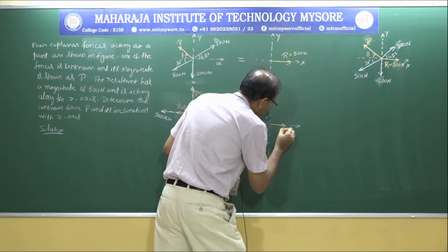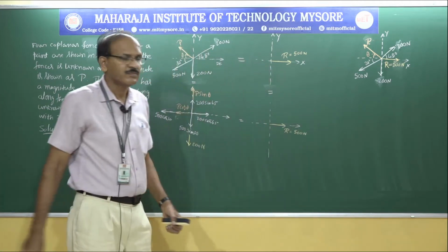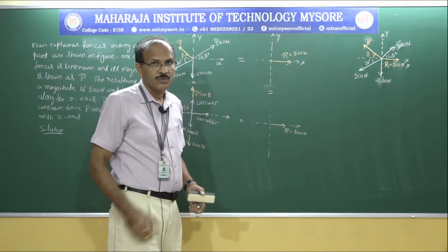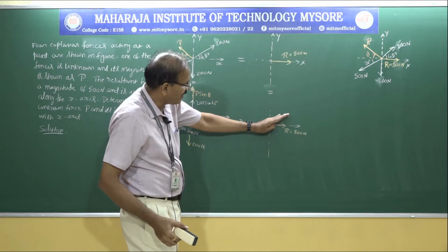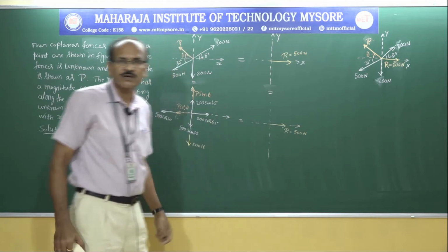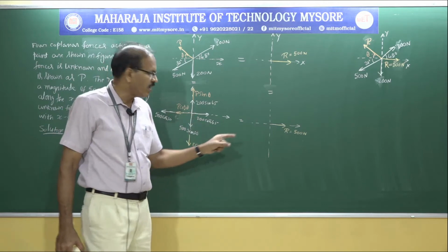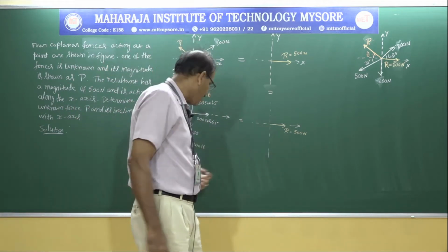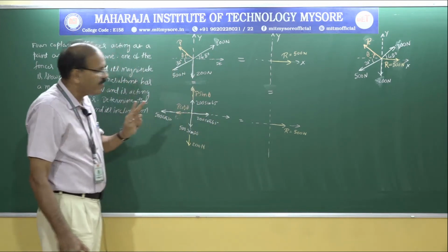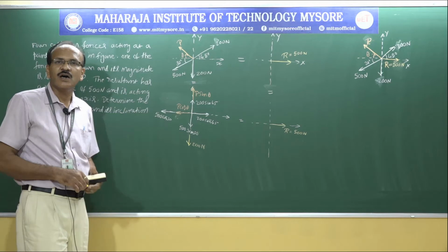R equal to 500 Newton. Okay. So the vertical component, yes, it is 0. As I said, if this had been inclined at a certain angle, I would have resolved the resultant into horizontal and vertical components. Now what I do is, I am going to take sigma Fx and equate that to the resultant. Next, sigma Fy, that should be equated to 0. So we will have two equations and two unknowns. Two equations, two unknowns, solve for the unknowns.